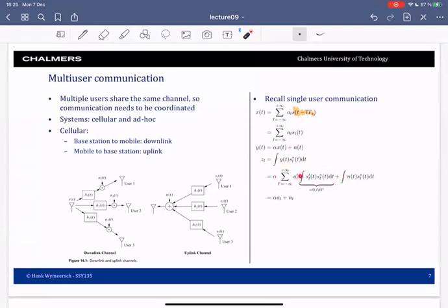So you have superposition of all transmitted pulses, a correlation between the l-th pulse and the l-prime-th pulse, and then the noise. And when these signals are orthogonal, which you would have if your transmit pulses are square root Nyquist pulses, then this becomes a Nyquist pulse. Then this correlation goes to 0, and then we recover exactly our l-th symbol plus noise.